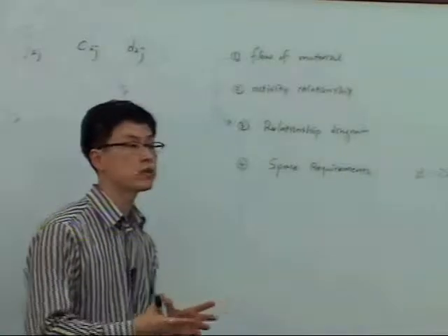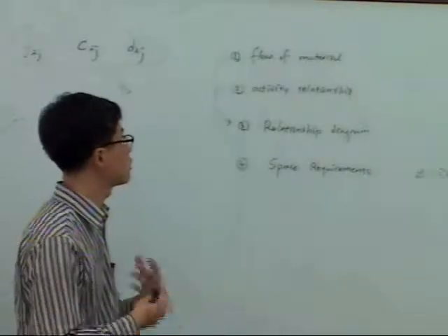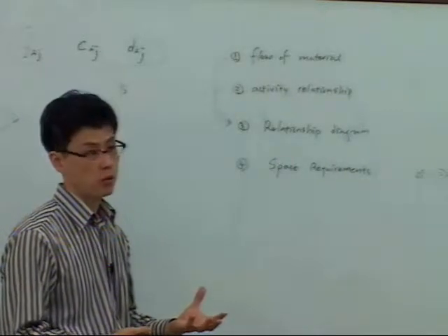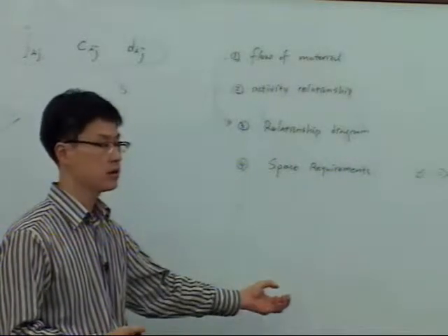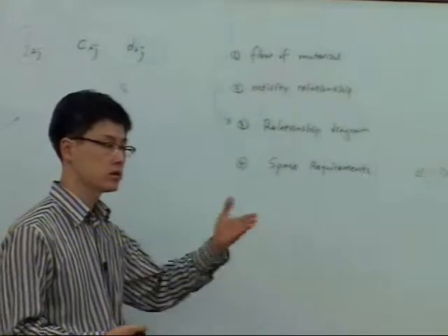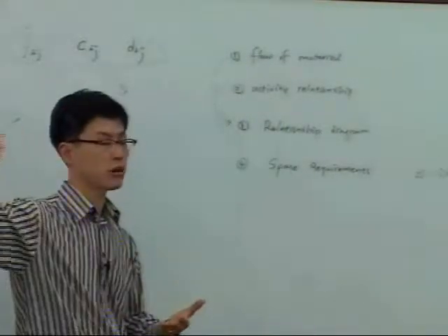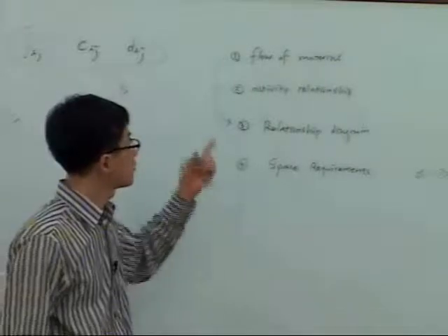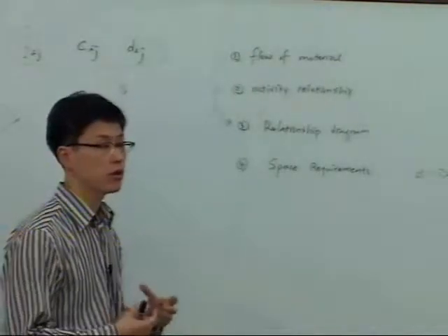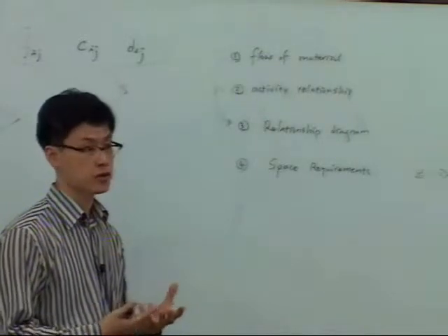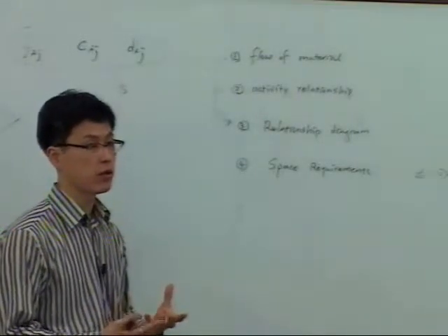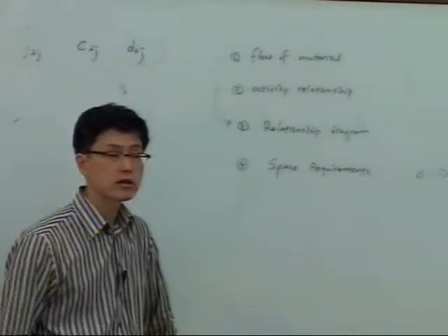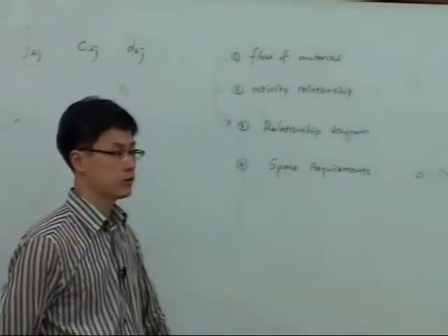And let's assume you're dealing with the surface preparation. And we know the material flow. Steel plate comes from the stockyard to me, and it goes to other fabrication shops most of the time. We know the flow of material, and we know the throughput, when you design a factory, right? Then you can calculate the space requirement.